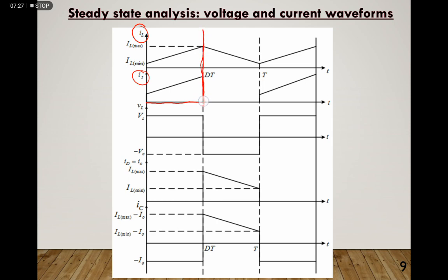In order to find the relationship between these two currents, to find the average quantity we can find the area under the curve. This is the shape of a trapezium. The formula for the area of a trapezium is half multiplied by the two parallel heights multiplied by the width, so we do this here.